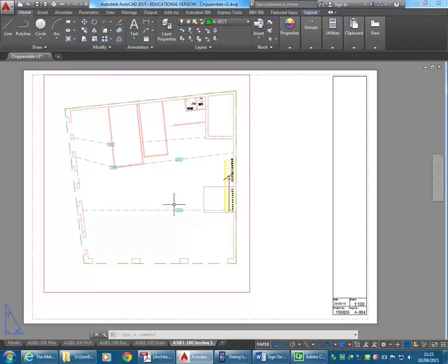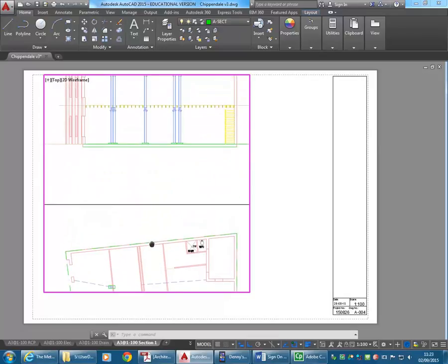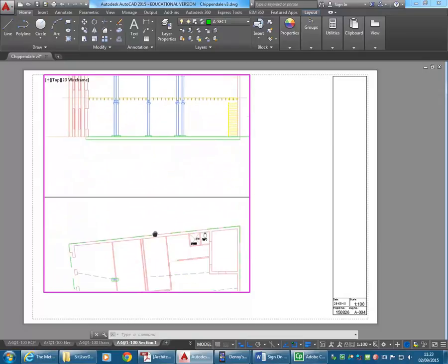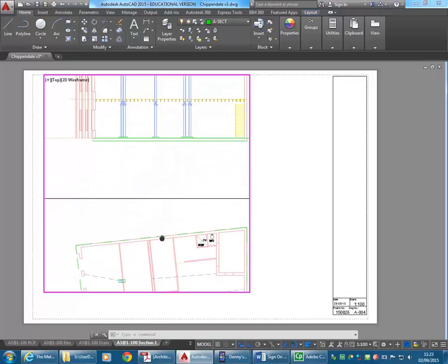And so now I want to adjust this viewport, so we'll click on the paper button to make it active, and then sort of show you a little extra command, because you can pan holding the wheel down, but notice how it's not going in a straight line because it's hard to keep the mouse straight, basically. I'll undo that.